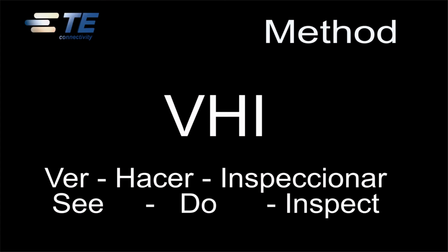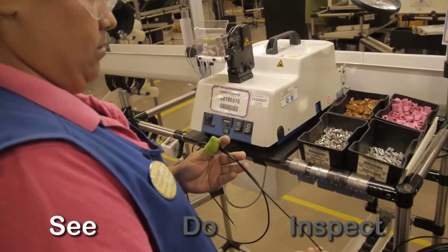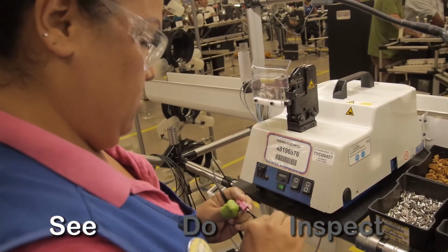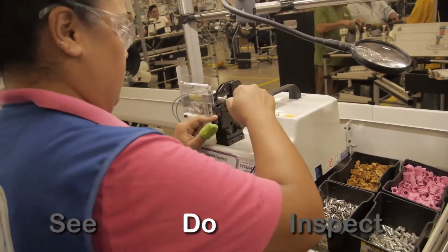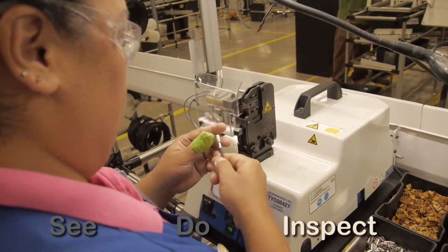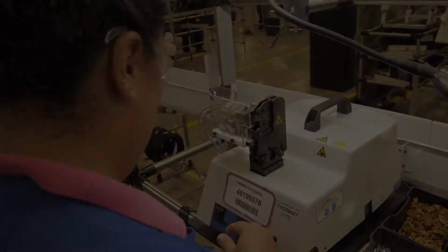All operators on the production line follow the see, do, inspect method. See. The operator on a station sees or inspects the product from the previous station. Do. If the part from the previous station is good, the operators perform the operation on their station. Inspect. Once the operation has been performed, the operator inspects the product before passing it to the next station.